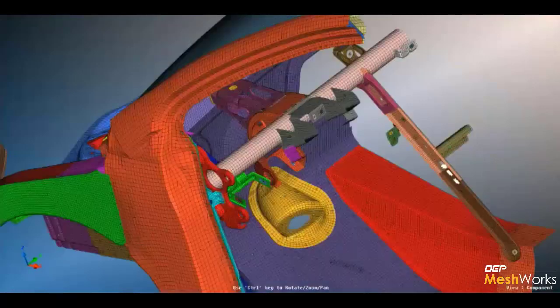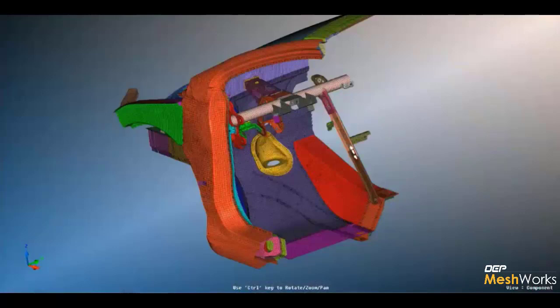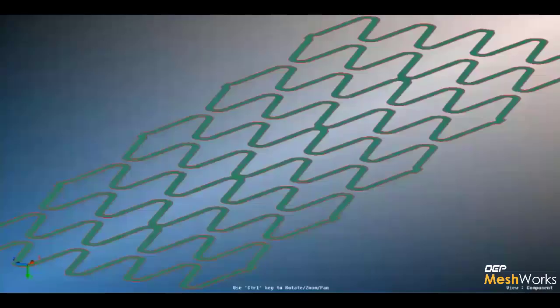It identifies all the rigid patches in the tools, and then we move on to identify the CNRB elements. Once all the elements have been identified, we can just click on the button called Convert Crash to NVH. This will enable a text pad stating that the process has been started. In a moment, I'll open the output model itself, as it is going to take a couple of minutes to do the conversion. So I've already exported the output model.